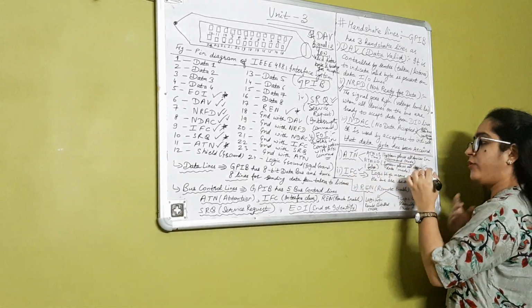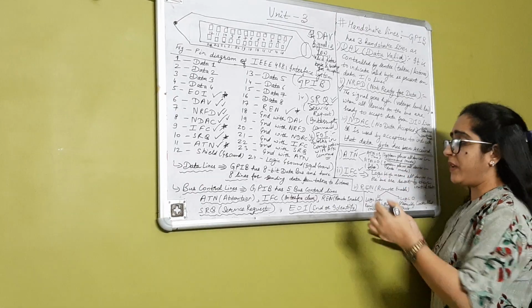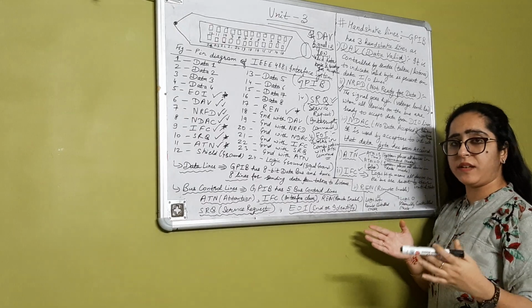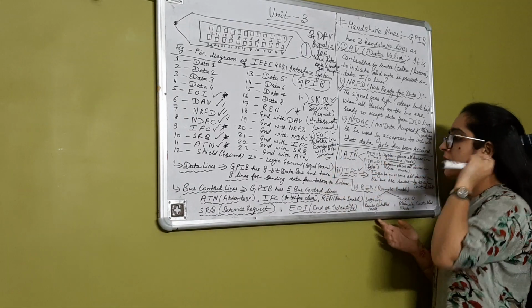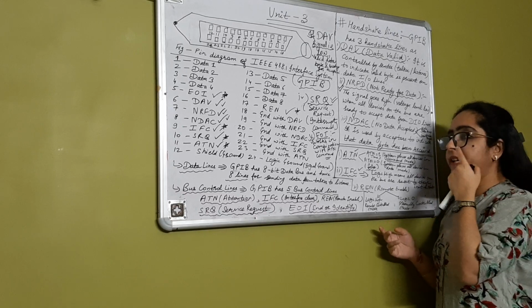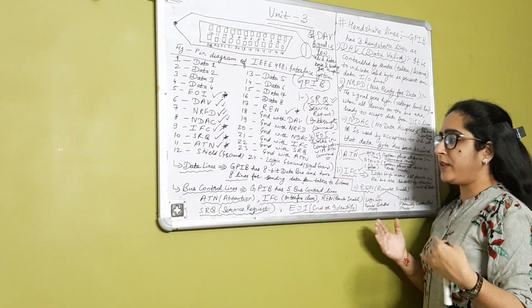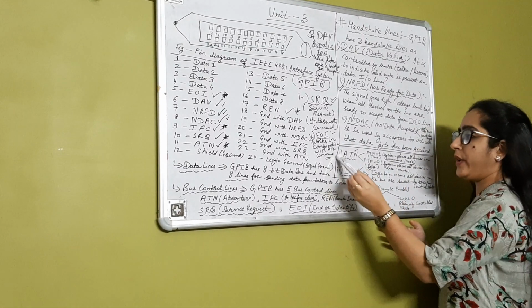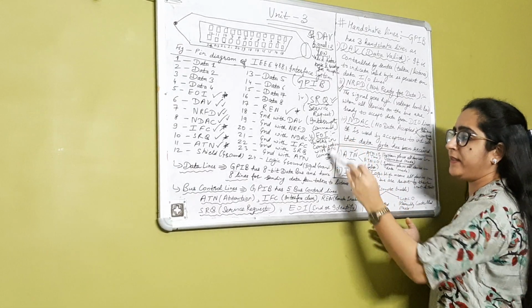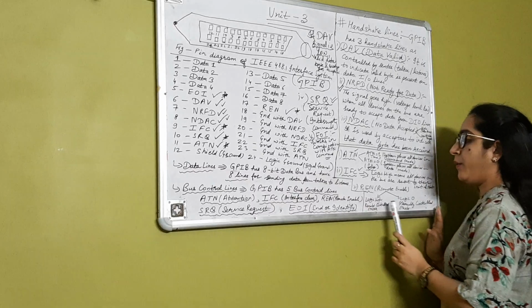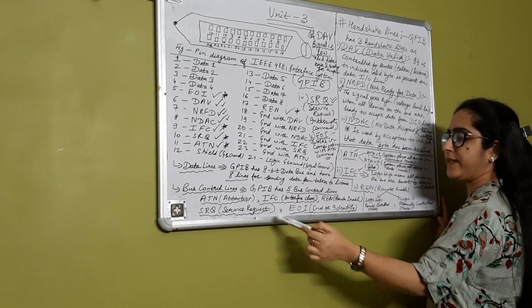So when ATN is true, it executes the polling sequences, one set of software programs for the controller, and if it is 0, then a talker can place the data on the data bus for transmission. Okay, and once the transmission is done, the device can send the end operation. Okay, now next, all the 5 bus control lines have been covered.